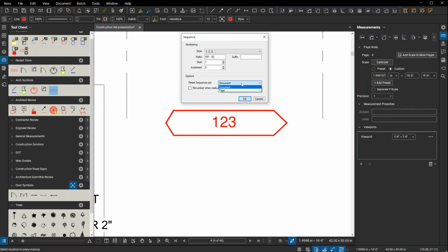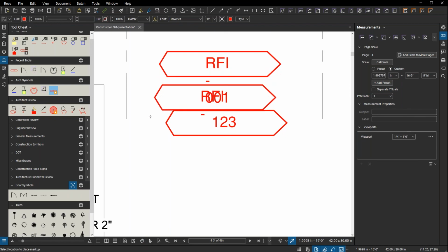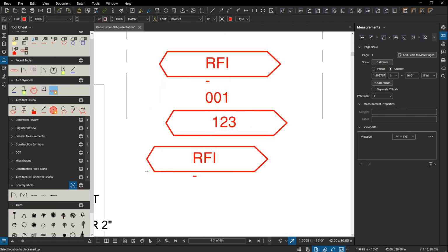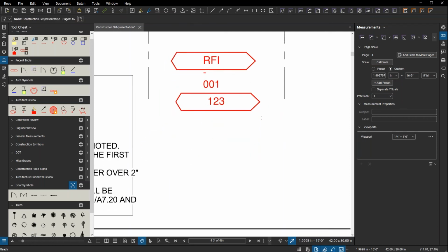And also your options for the numbering scheme being used is a sequence per page or for the document. You choose. So now the new symbol here defined, it may be hard to see on screen. It's almost like a backwards play arrow here. When I select this and add it in, it brings in the tool onto my sheet and it'll number those for me. I didn't make my text window wide enough, but you get the idea.